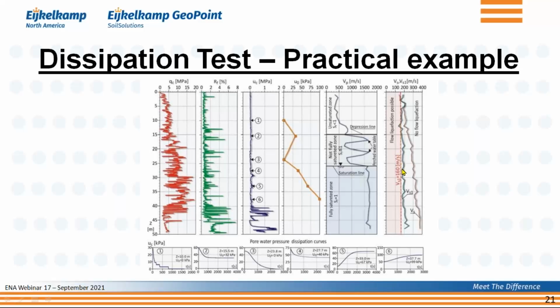And what you can do with that is get an indication of whether liquefaction is possible or whether it's unlikely. There are different correlations for that, also described in that book that I mentioned a little bit earlier, that was put together by Peter Robertson. So now suddenly we can also figure out whether this hydraulic effect can cause liquefaction. So that just gives you an idea of what you can do with the cone to do this hydrogeotechnical survey.